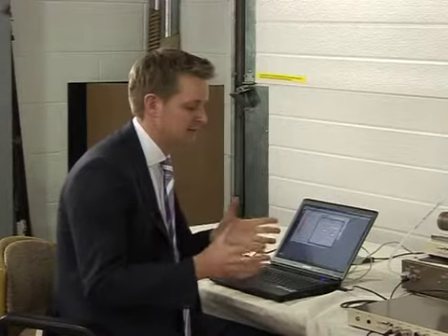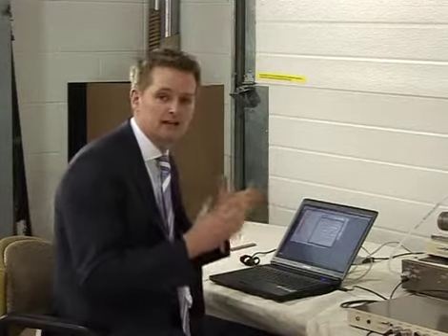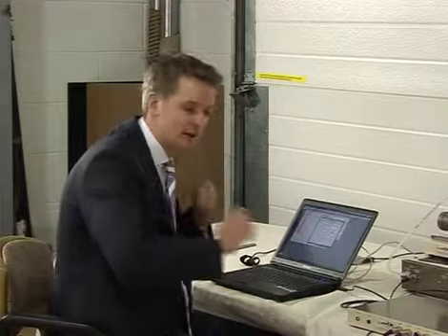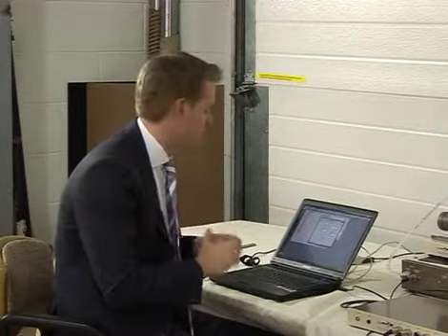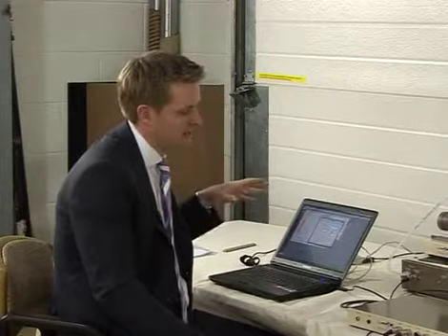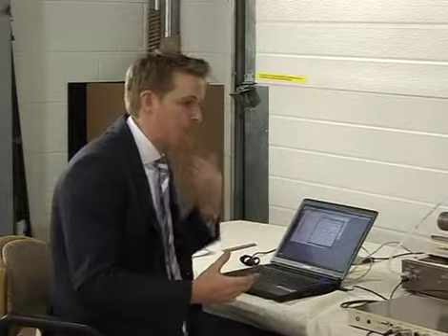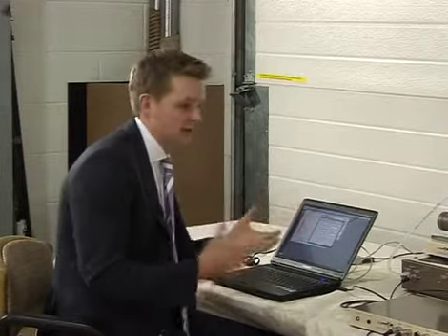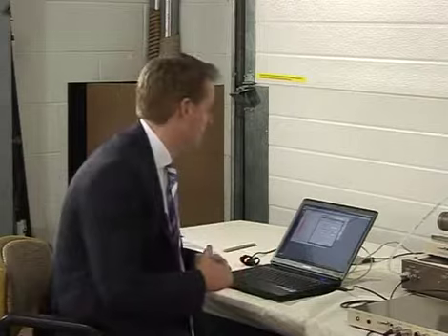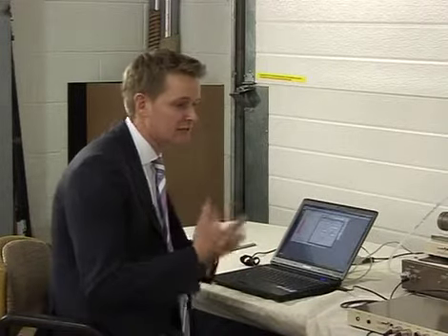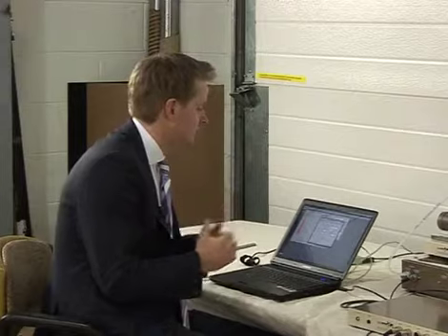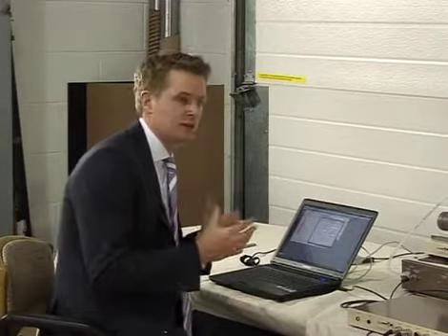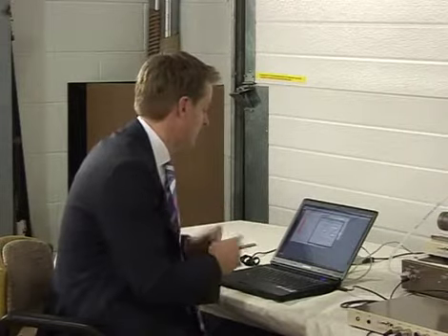And as we've seen, the data comes back into GDS Lab at a slower rate than the test actually runs at. So if we know we have a very long test that's going to last a number of hours, we can set to maybe save 2 cycles in every 10, or maybe 10 cycles in every 50, by having the number of cycles on as 10 and the number of cycles off as 40. This allows us to run the test much quicker because there's not so much data to extract back, whilst hopefully still having a representative number of cycles for that long test.